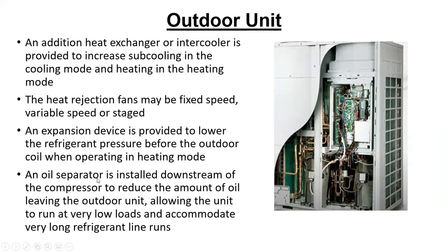And oil separators are installed downstream of the compressor to reduce the amount of oil leaving the outdoor unit, allowing the unit to run at very low loads and accommodate very long refrigerant line runs. These things can have hundreds of feet of distance between some of these units. And when you get into this video, if I have it all in here or not, they give elevation distances and horizontal distances and all that sort of thing that the designer would need to know when laying out a system.